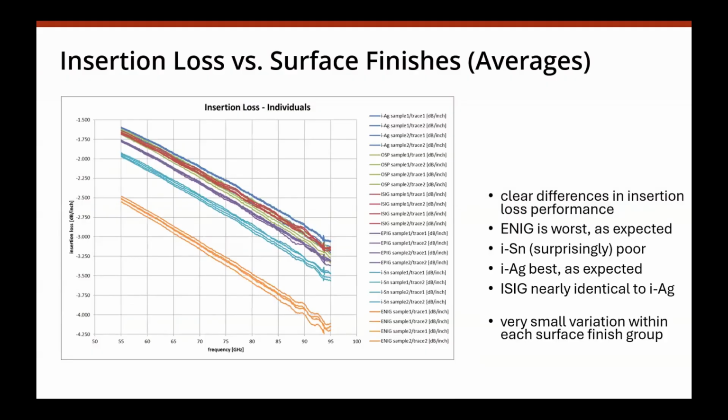And finally, if you talk about outer layers, of course, there's a metal surface finish on the traces, on the pads. For many, many years, nickel gold-based finishes had been the traditional choice because they were so easy to handle and very stable, hard to damage. But the downside is they created additional losses, and that's the orange traces at the bottom. That's ENIG, and because of the nickel in that surface finish, you create higher losses at higher frequencies.